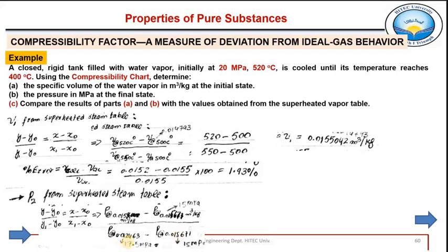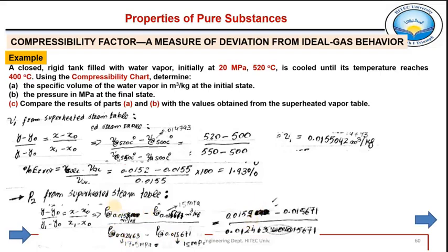So our desired pressure is between, P at this volume. This is the unknown pressure at this volume, and this is the known pressure at this volume from the steam table, which is 17.5, and this is the known pressure at this volume, which is 15 megapascal. And the X values are the known volumes. X is the volume V2 at which we want to calculate this P. Corresponding to this pressure, this is the volume. Corresponding to 17.5, this is the volume. Corresponding to this pressure, this is the volume.